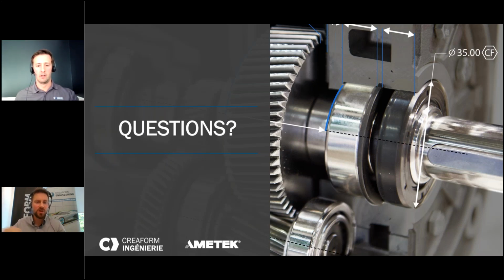So you say, let's just track it, measure it, and use statistics to make sure we control the whole process. We cannot control how we play with that tolerance, but we can control the process. So at least we are sure we're going to be good 99.97% of the time. That could be okay, and then you can evaluate the cost of that.